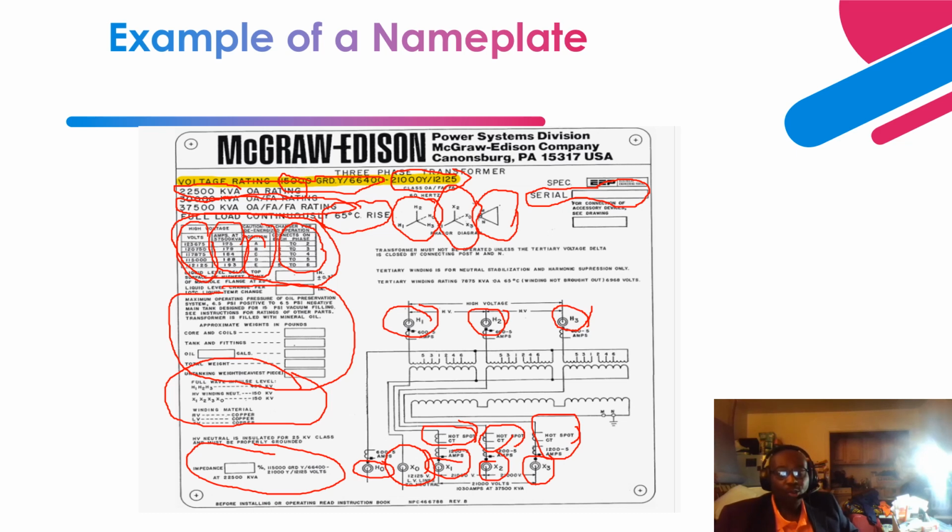So there are two components that you utilize to determine the hotspot. The first one is utilizing the CTs that are located in the low voltage winding in each phase, that basically mimic or determine the amount of current that is being carried by the load. And these CTs are integrated to a heater. So that heater heats up and mimics a corresponding temperature. Then there is a gradient temperature that is added to the measured temperature from the heater, and that determines your hotspot temperature.